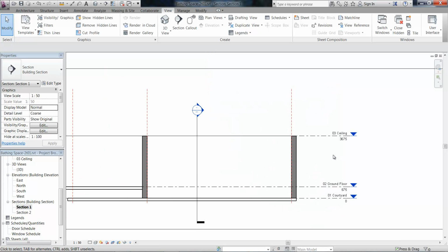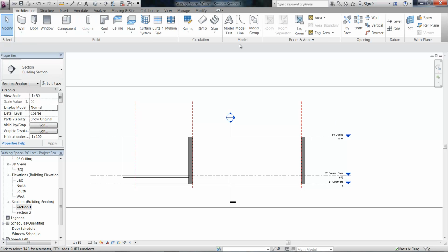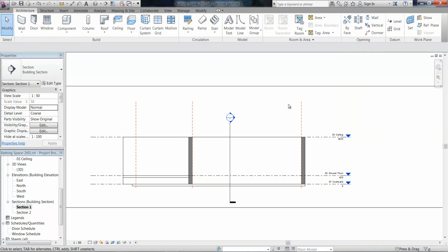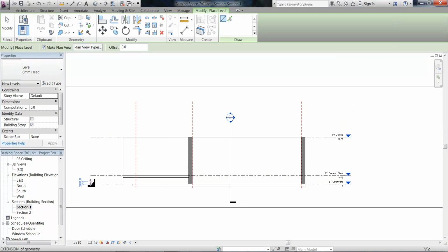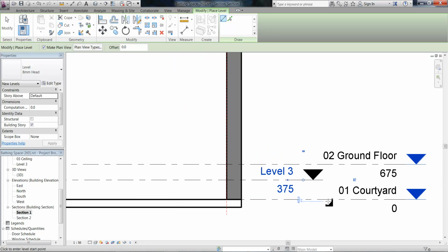So these are things you want to maybe start thinking about as using the software, the fact that scale is going to affect things like your notes, and you don't need to change the height like you would in a program like maybe Word. So think about how scale works. And now I'll go to the level tool on the architecture tab and just click 2 points either side of the building to make a new level, which I'm going to call 02 bathroom.